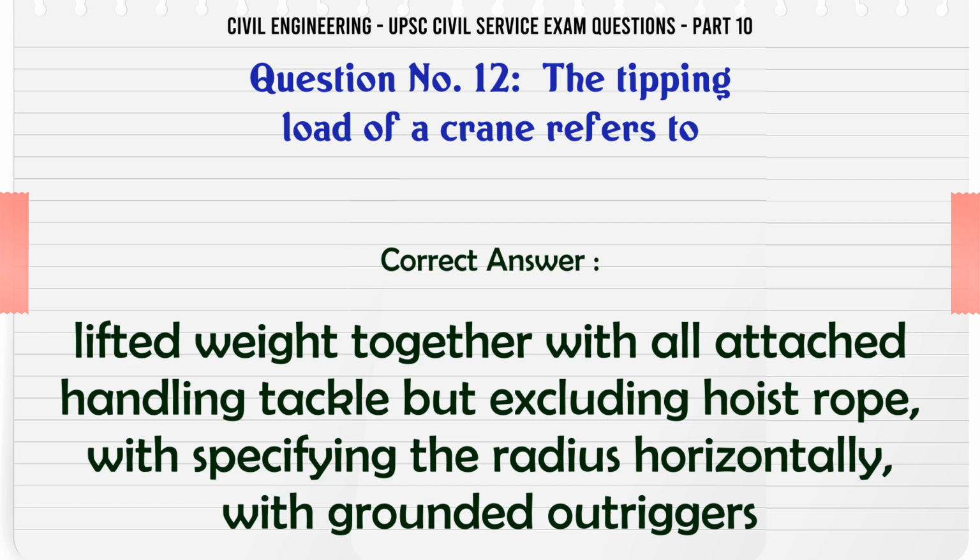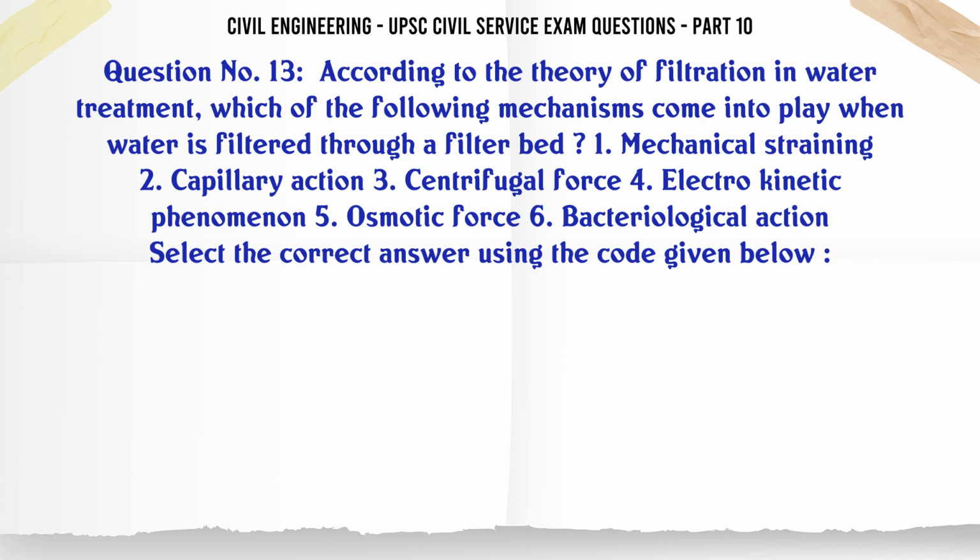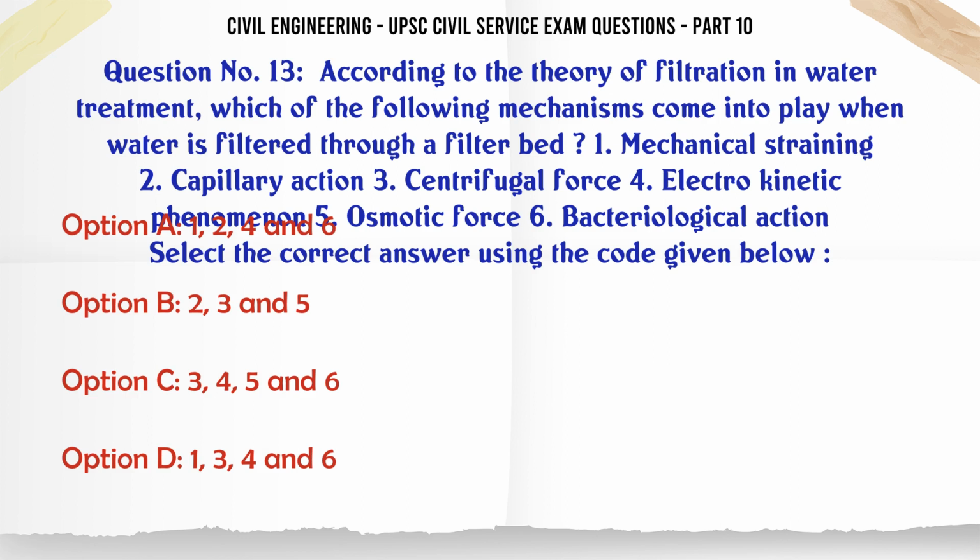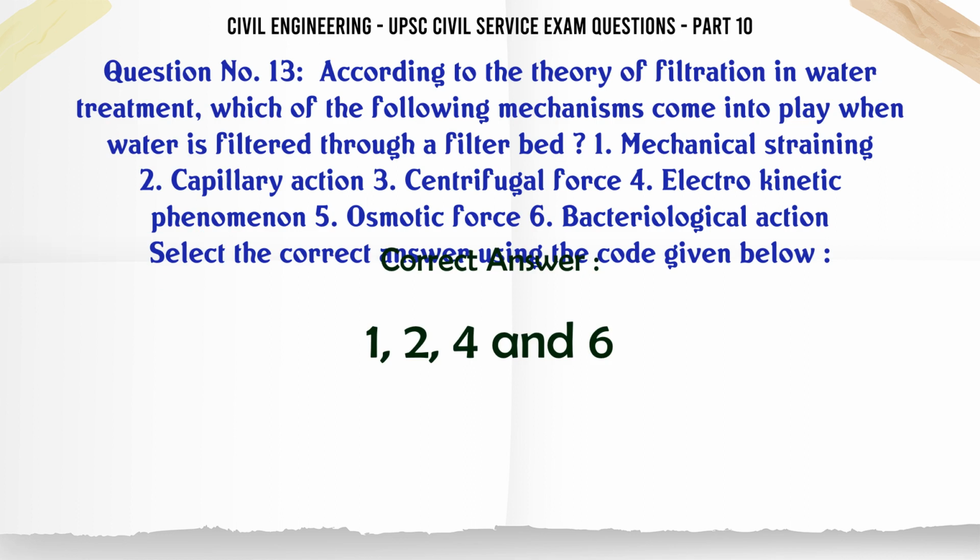horizontally with grounded outriggers. According to the theory of filtration in water treatment, which of the following mechanisms come into play when water is filtered through a filter bed? 1. Mechanical straining. 2. Capillary action. 3. Centrifugal force. 4. Electrokinetic phenomenon. 5. Osmotic force. 6. Bacteriological action. Select the correct answer using the code given below. A. 1, 2, 4, and 6. B. 2, 3, and 5. C. 3, 4, 5, and 6. D. 1, 3, 4, and 6. The correct answer is 1, 2, 4, and 6.